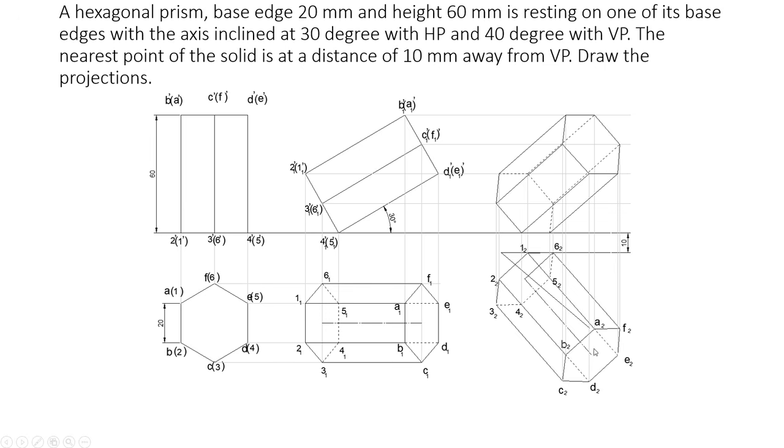Now the face which is coming towards the observer is here. So this is the front view. So the face which is coming towards the observer is visible here. So this face is facing the observer, and this face is facing the vertical plane. So the face which is facing the base, which is facing the vertical plane, will be invisible. So first you mark this face is visible. So first you mark the visible base face like this. Then you draw the border like this.